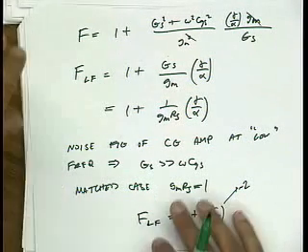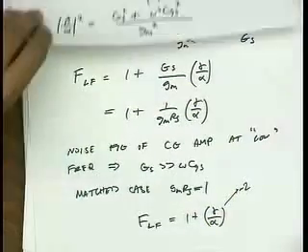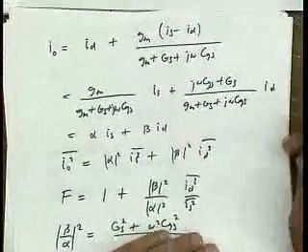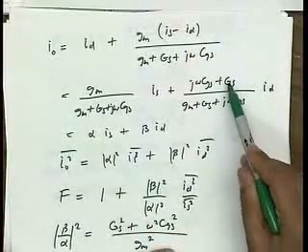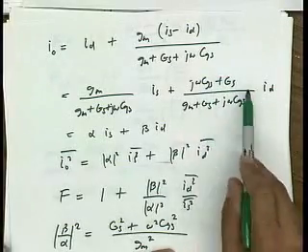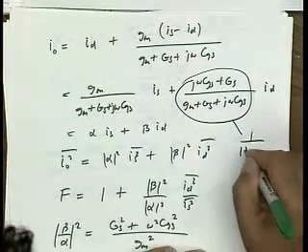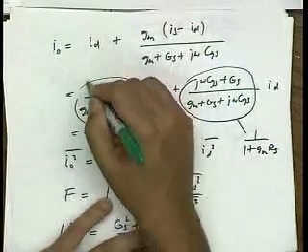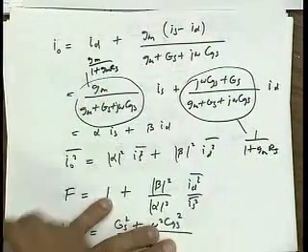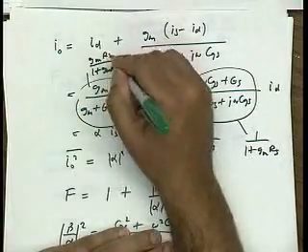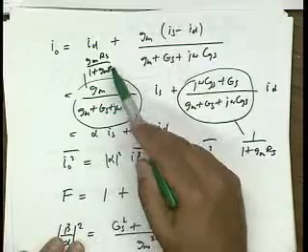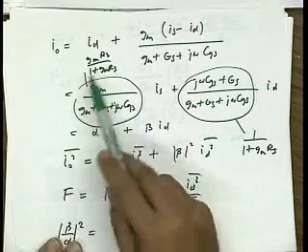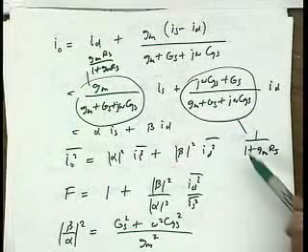Now, there are a couple of interesting things that come out of this calculation. If I come back here, I notice a pattern: the drain noise is at low frequencies attenuated by this factor 1 plus gm RS. So at low frequencies, this is 1 over 1 plus gm RS. And at low frequencies, this term is gm RS over 1 plus gm RS, which is approximately 1 as the loop gain becomes large. So as the loop gain becomes large, all the source noise makes it to the output, but the drain current gets rejected.